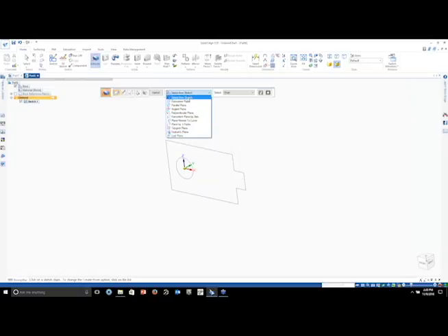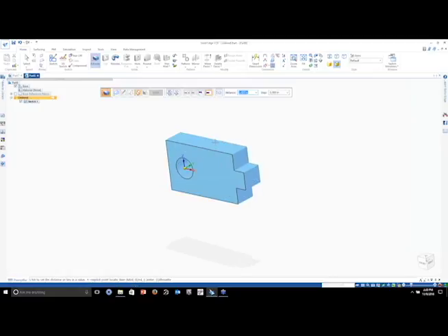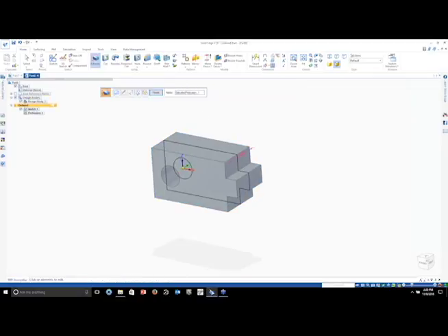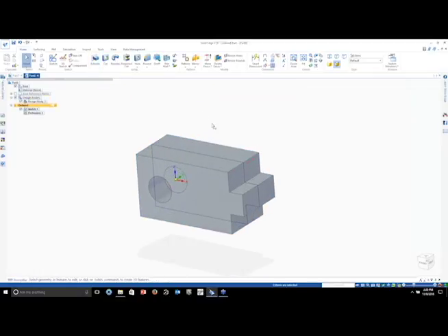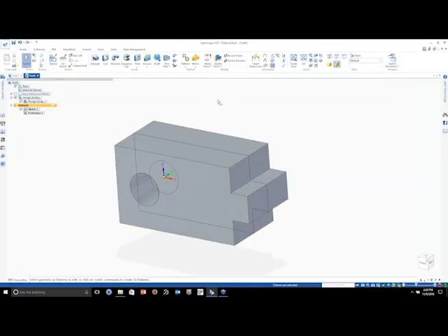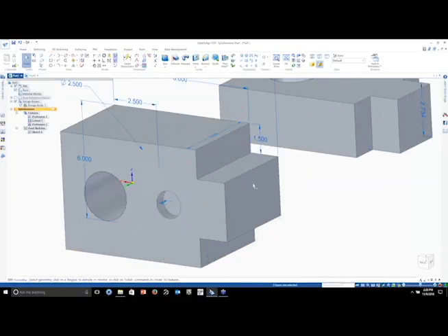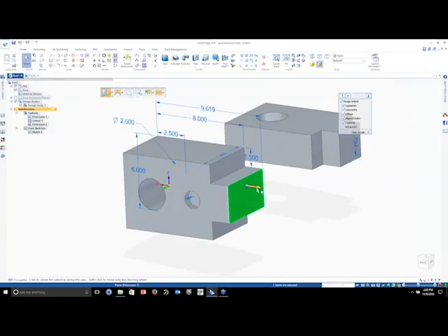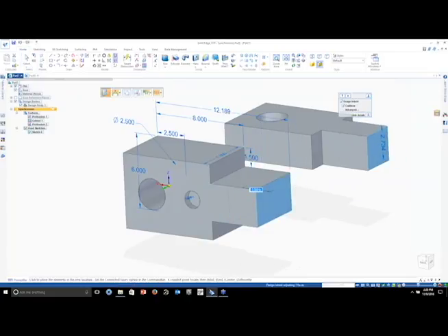All right, so again, now we're going to tell it whether we want to make a revolve feature from it, an extruded feature. I come over here and now say extrude. I have a sketch already on screen, so I can just say select sketch, and grab my sketch features, grab them both, and of course, make them both symmetric. And there we have it.